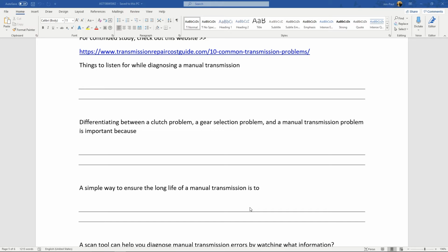When we spoke about the clutch last week, the part that moves is that throwout bearing. And if it's constantly pressed against the pressure plate, it's wearing itself out. Whereas normally, you let the clutch pedal go, and the pressure plate squeezes everything together. So the pressure plate is really supposed to handle the load. The throwout bearing shouldn't be engaged very often. So if you come to a red light and you leave the transmission in first gear and you push the clutch in, of course the engine will be fine, it's disengaged, but you'll wear that throwout bearing out quickly. So it's one of those things you try to not have the clutch engaged when you're not using it.